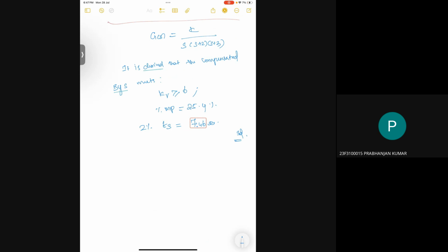Okay. First question is, what is the real part of the dominant poles? First, you have to find the dominant poles using the given information. Then you have to say what is the real part of the dominant poles. The exact question is that. So with this information, we know percentage peak overshoot will deal with only zeta.